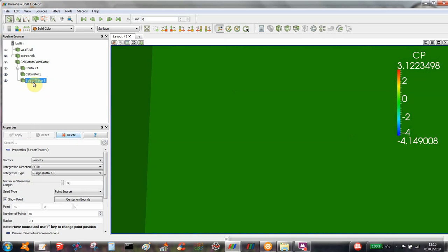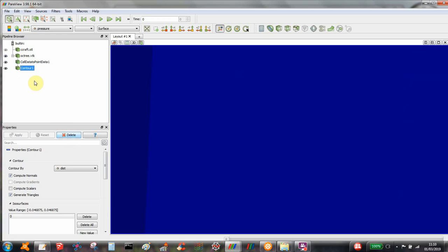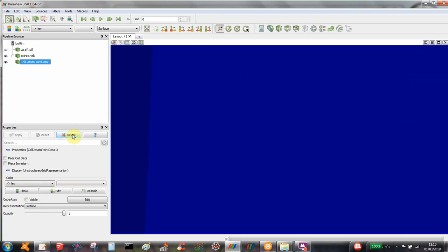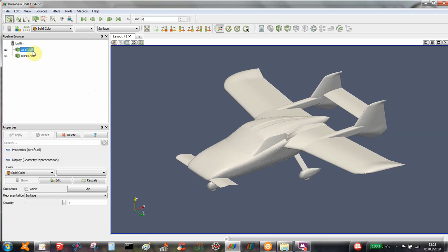And the other thing I wanted to show was, get rid of some of these contour. Yeah, if you're not comfortable using the distance field surface, the alternative is to interpolate the flow solution back onto the original STL file, which is quite handy sometimes.